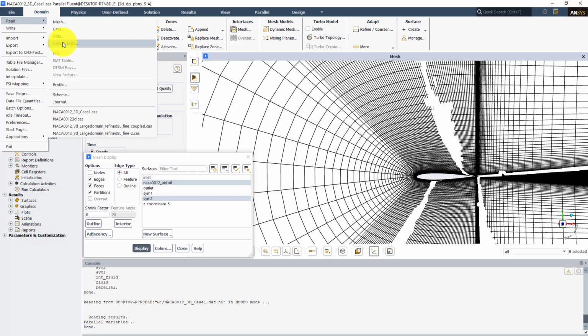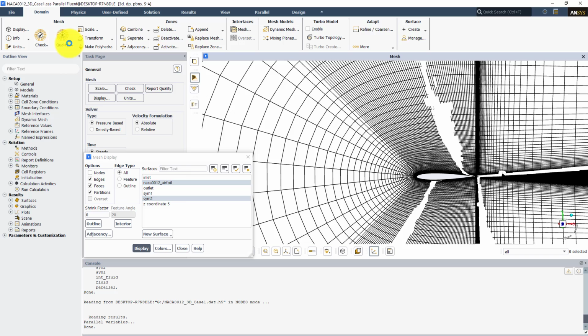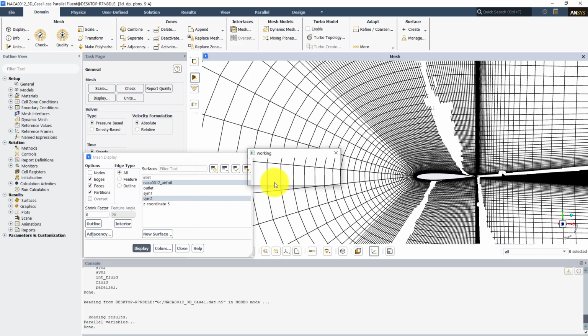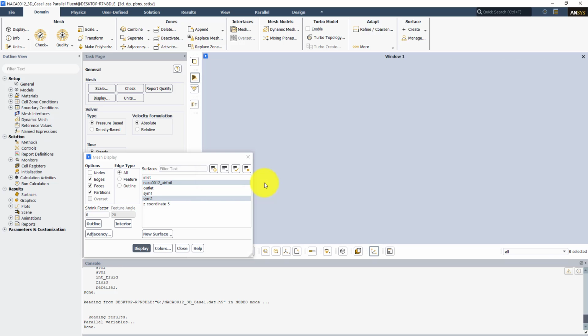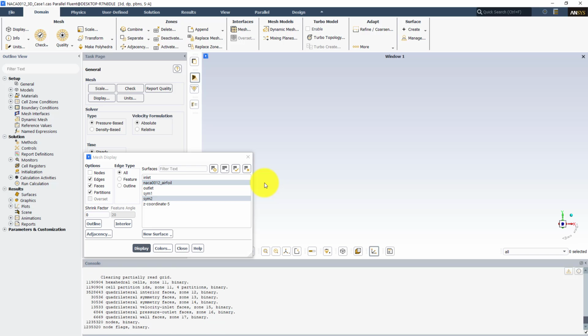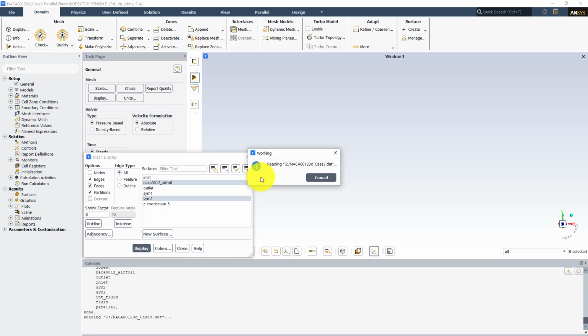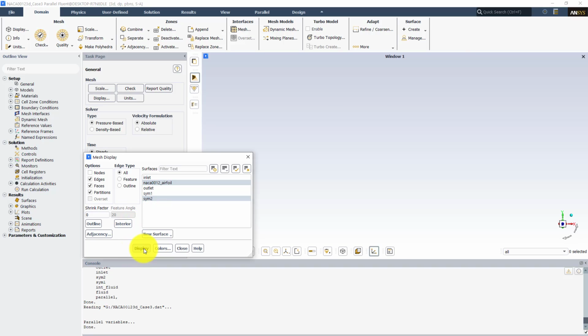And now I'm going to read case number 3, which is case number 4, but the run will be done in the new version of Fluent. So I'm going to read the old version file, which is the Fluent 2019 release 3 file, and the partitioning was done very nicely in that case. So in my point of view, we should stick to the 2019 release 3 version at the moment, unless we get a solution for this problem.